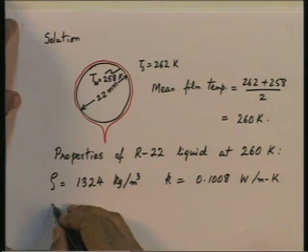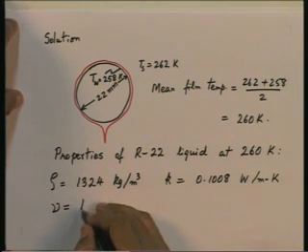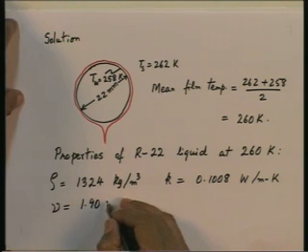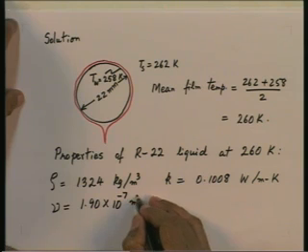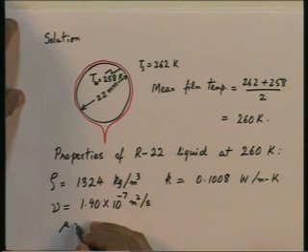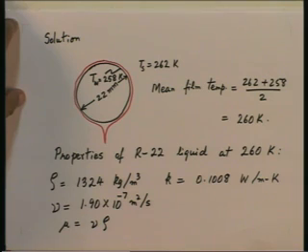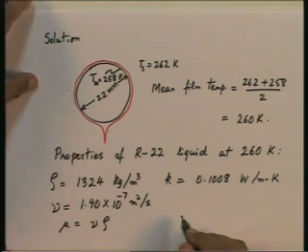In the tables that I looked up, the kinematic viscosity was available. So, nu, which is 1.90 into 10 to the minus 7 meter squared per second. You can always get mu once you know nu, because mu is equal to kinematic viscosity into density. So, these are the three liquid properties we will need.